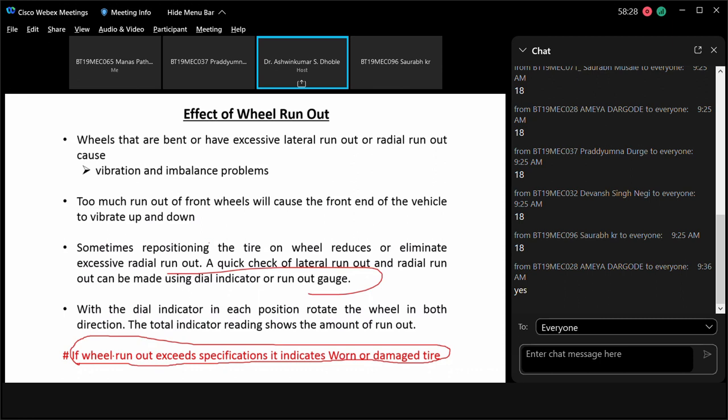So the problem was with that particular elbow which had a hair crack. When I used to drive the vehicle, there used to be some leakage through it. But since the vehicle was in hot condition and the crack was very minute, the fluid used to evaporate, leaving no trace of leakage on that joint. Somehow I could fix that problem for only 300. I just changed that component, and now there has been no problem of overheating for the last 4 years.